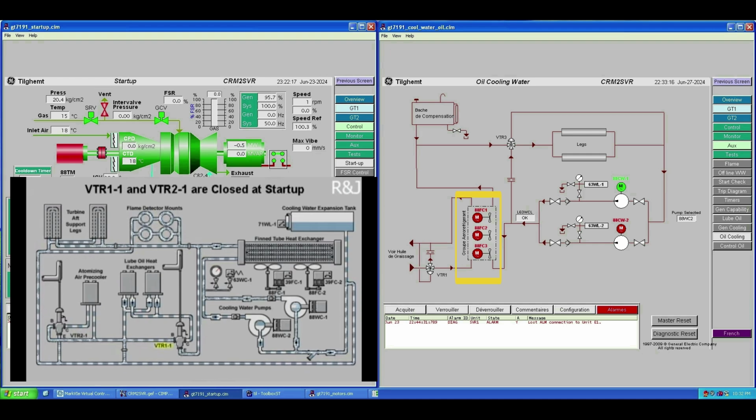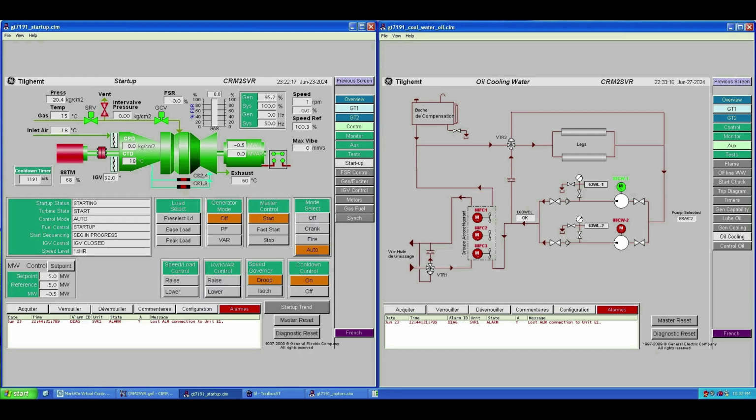The oil cooling fans are supposed to start after 88BA1 and 2, and before the opening of the fire dampers and the starting of 88BA3, 4, and 5. Anyway, the temperature control valve VTR1 doesn't let oil pass through the fans until it reaches a certain temperature, and that's the correct time for the cooling fans to start. VTR3 opens to compensate for water loss in the system.